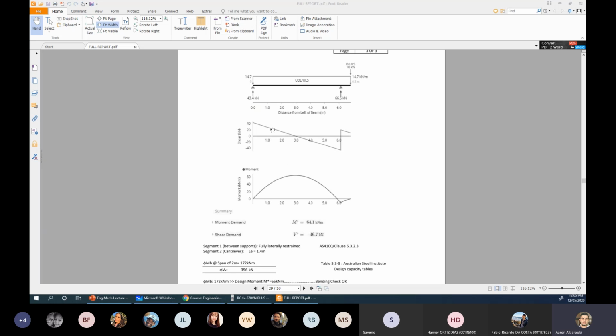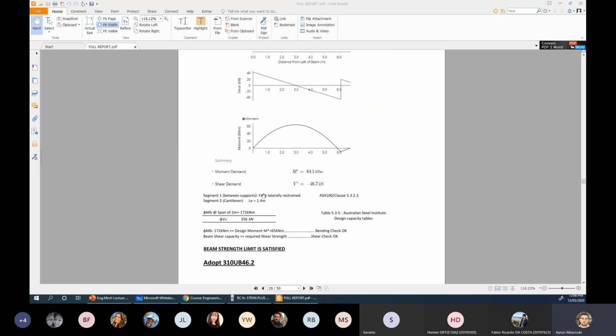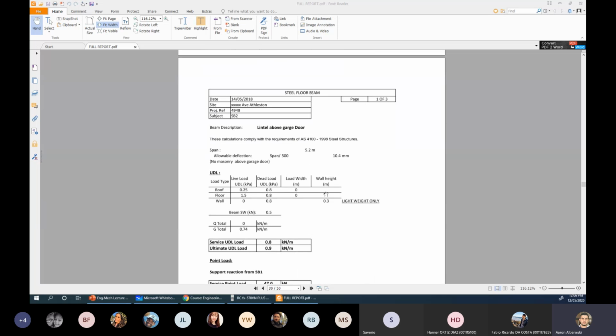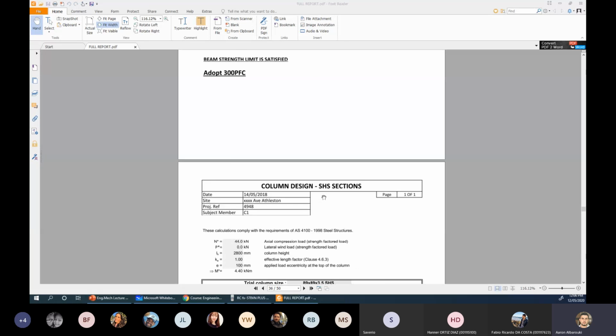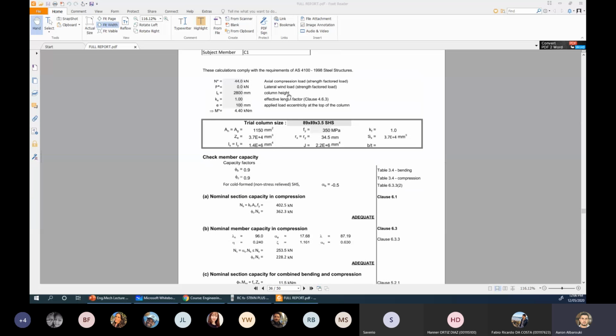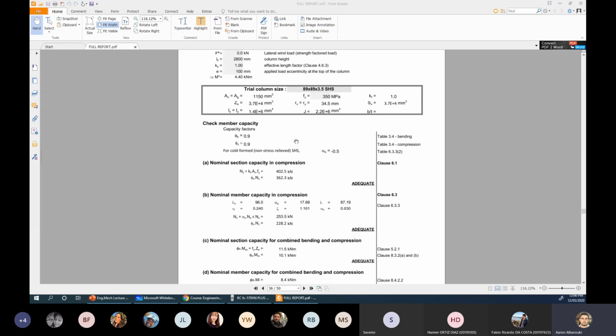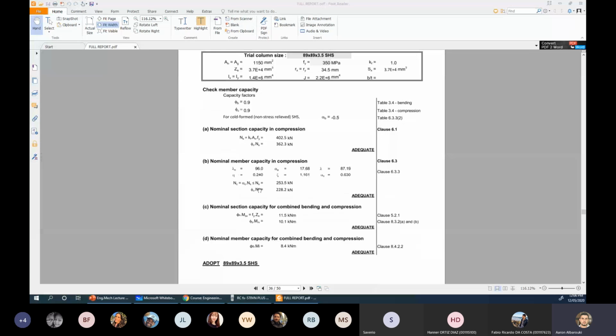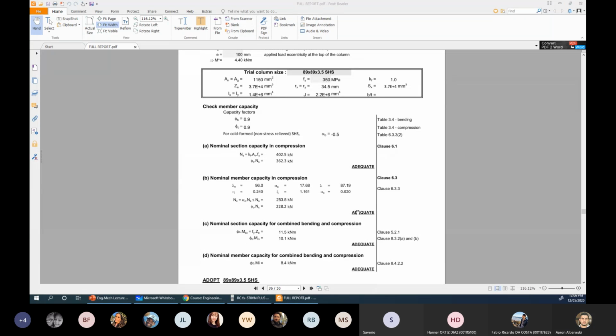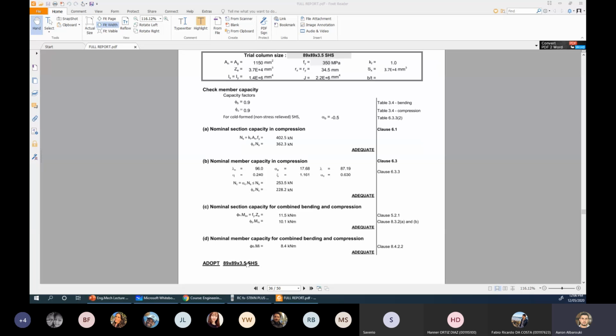From this understanding, that's what we're learning today. This is called the shear force diagram and bending moment diagram. From the shear force diagram and bending moment diagram, we can always say I've got the maximum, I can look at it and quantify it. This is the maximum moment. This is the maximum shear in my beam. Then I have to go through the second process of doing the steel design, which is a slightly different process, which we're learning next year. These are the formulas that you'll be learning next year just for designing the steel members. A trial of 89 by 89 by 3.5 square hollow section. These are the properties, this is the calculation on it, and we see whether it meets the applied axial force and bending moment. Is it adequate or not adequate? And then we agree, do we choose it or not, okay?